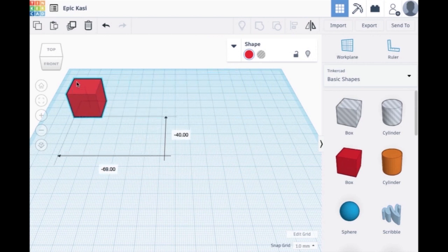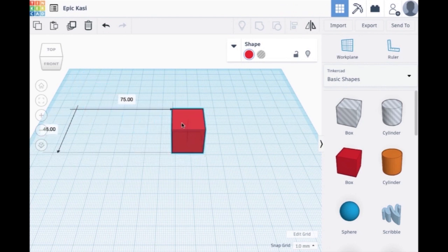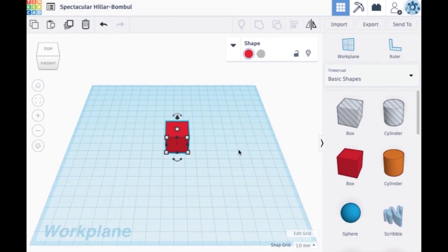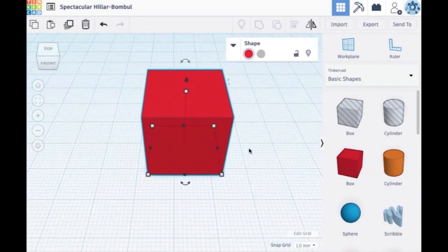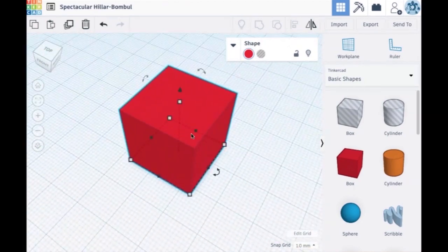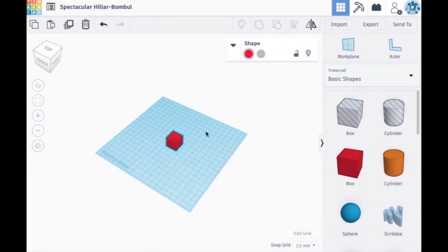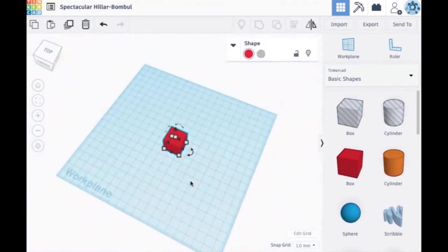When you're happy with its new position, release the mouse button. Now would be a good time to try practicing looking at your objects from different angles. Click down on the right-hand mouse button and move the mouse to see your object from different angles. Try zooming in and out. Try looking at it from below or from above. When you're ready to continue, click on the Home icon.